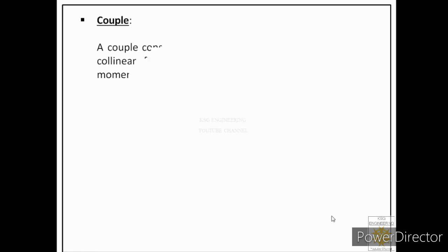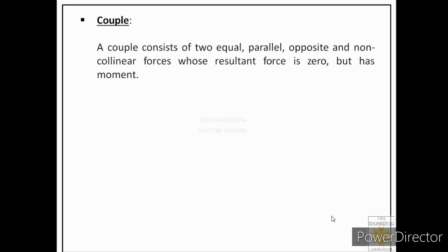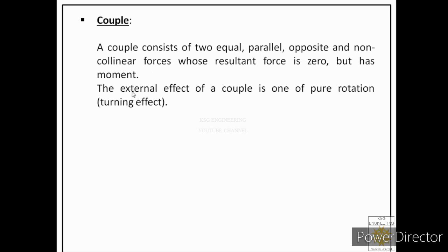Let us first see what is a couple. A couple consists of two equal, parallel, opposite and non-collinear forces whose resultant force is zero but has moment. The external effect of a couple is one of pure rotation. So let us understand this through an example.